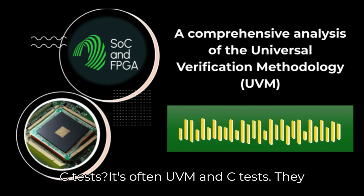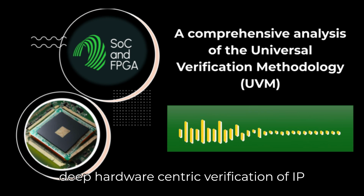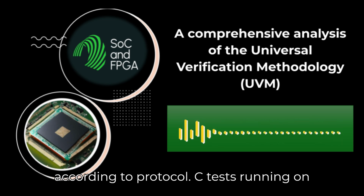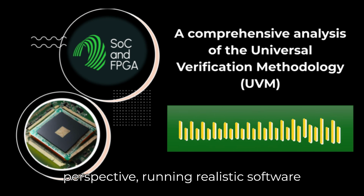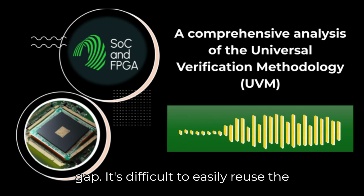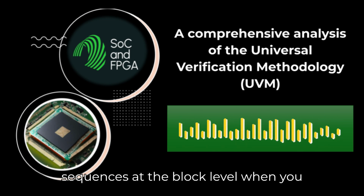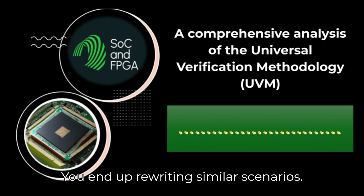It's often UVM and C tests. They have different strengths. UVM excels at deep, hardware-centric verification of IP blocks and subsystems, wiggling every pin according to protocol. C tests running on an embedded CPU model are better at verifying the system from the software perspective, running realistic software flows. But there's a gap between them. There is. It's often called the UVM to C gap. It's difficult to easily reuse the verification intent you developed in UVM sequences at the block level when you move to writing C tests at the SoC level. You end up rewriting similar scenarios.